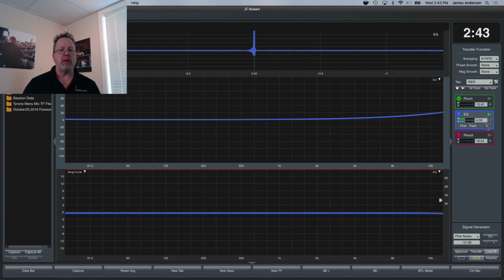Okay, so that was kind of cool though. If any of you have ever done azimuth adjust for tape heads, so a lot of people watching this, unfortunately, never had the pleasure of aligning tape heads. But basically, you might know that process from the XY on an O-scope. You're just trying to get that phase trace flat, and that tells you they're in time. A flat phase trace says everybody's in time, everybody's arriving together.